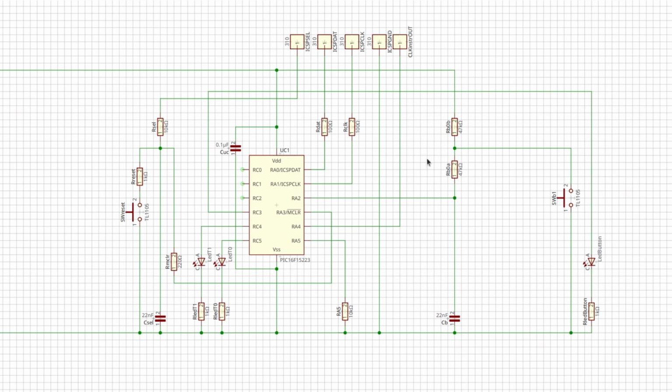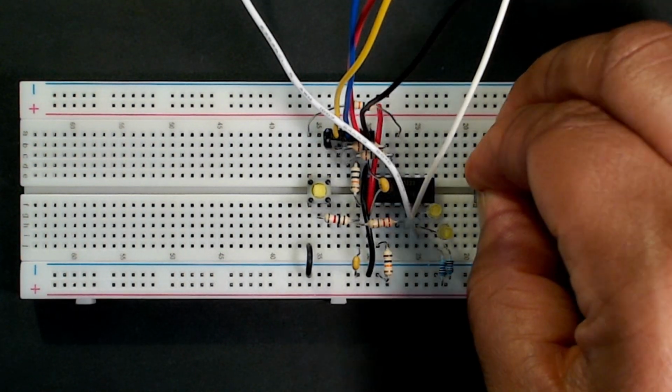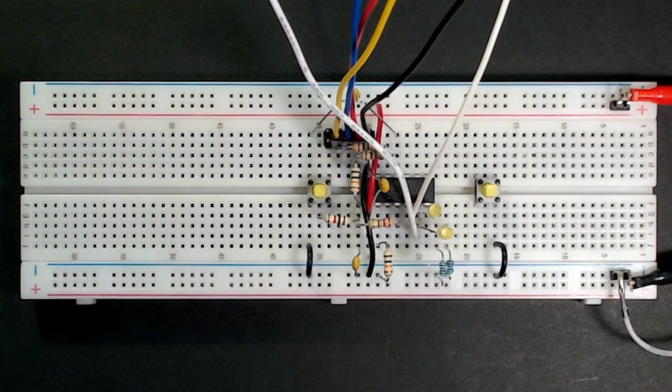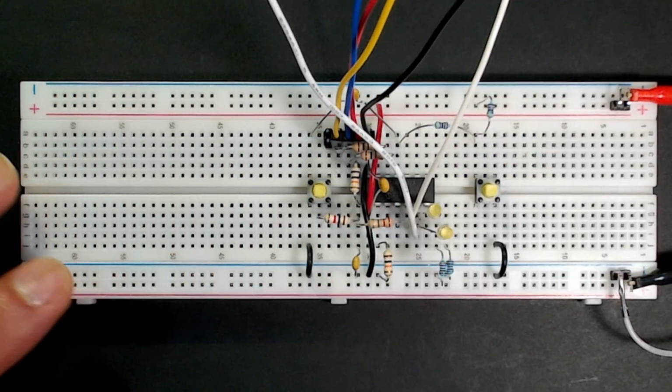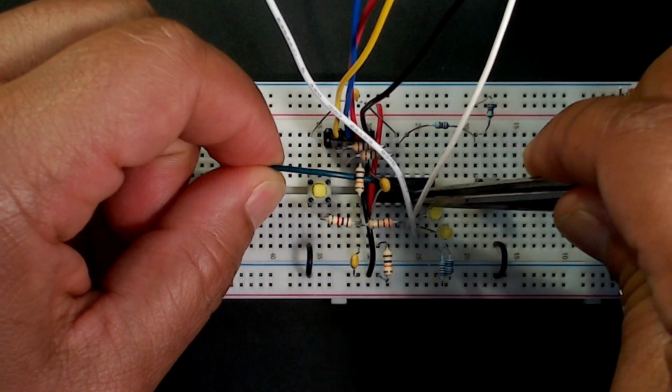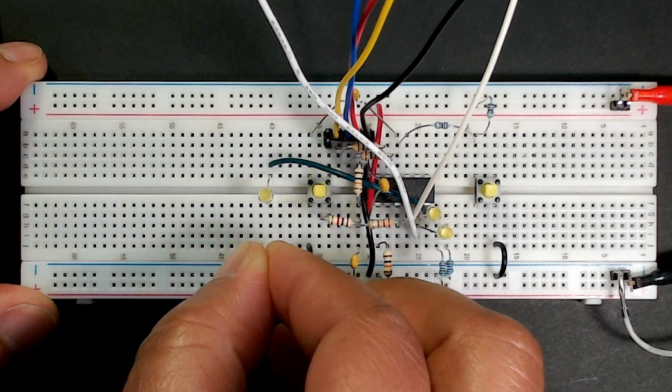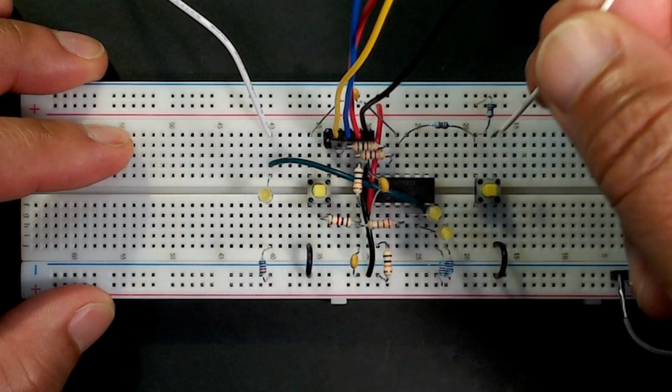You can see the hardware debouncing circuit that we used here, 2 47 kilo ohm resistors and a single 22 nanofarad capacitor down here. We also have a new LED here grounded through this 1 kilo ohm resistor connected to RC3. We're going to use that LED to observe the button presses. Let's wire it up. With that all wired up, let's move on to the assembly code.